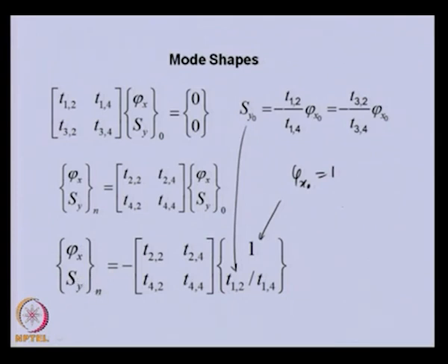If we see the boundary condition at the nth disk, we have linear displacement 0 because this is a simply supported case, and the angular displacement we can get from here, because now phi x n will be given by the first equation here.